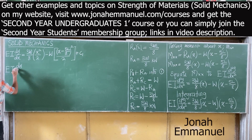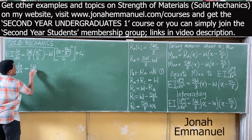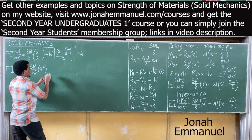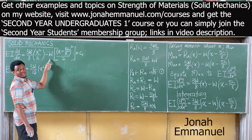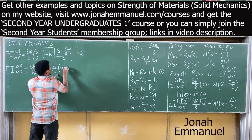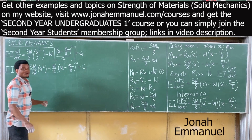Proceeding with this, I have EI dy/dx. It's equal to, what do I have here? 3W over 8 times 2, 16, into x squared, minus, what do you have here? This one comes down here, becomes W over 2. So I have W over 2 into x minus 5L over 8 all squared plus C1.